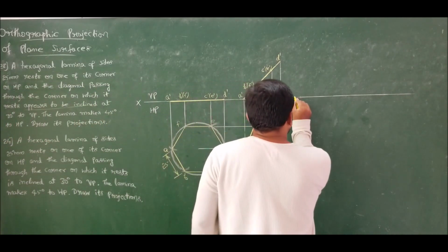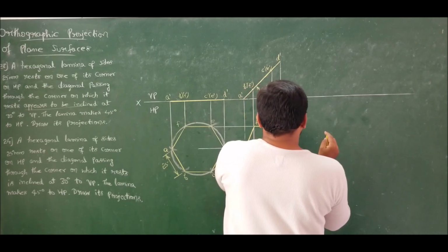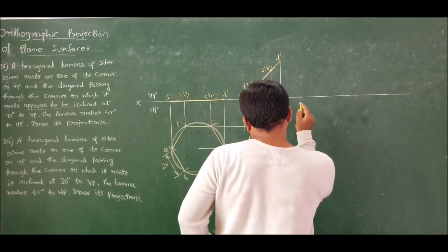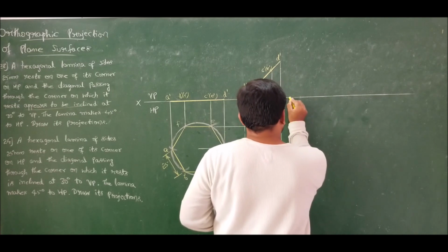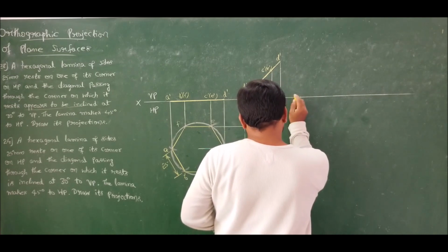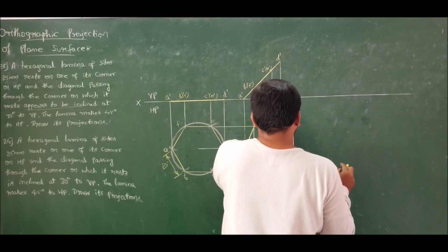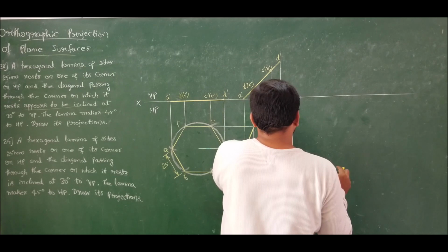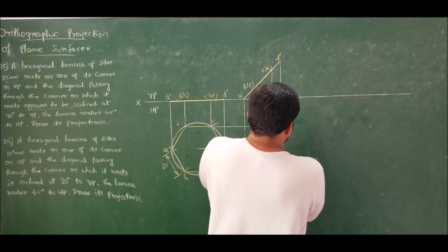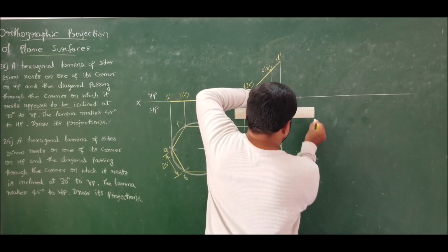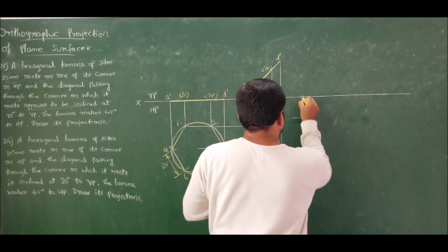So directly you take 30 degrees. If I take 30 degrees and incline, there is a chance that FE might enter the vertical plane. So for the safer side, let me offset the XY reference line, and these two are parallel.